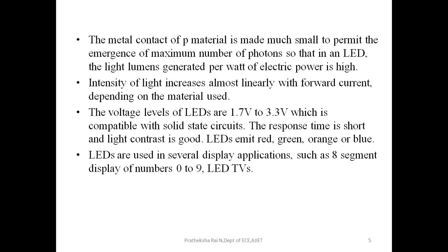Thus the actual color of a light emitting diode is determined by the wavelength of the light emitted, which in turn is determined by the actual semiconductor compound used in forming the PN junction during manufacture. Therefore, the color of the light emitted by an LED is not determined by the coloring of LED's plastic body, although these are slightly colored to both enhance the light output and to indicate its color when it's not being illuminated by an electrical supply. Light emitting diodes are available in a wide range of colors, with most common being red, amber, yellow and green, and are widely used as visual indicators and as moving light displays.